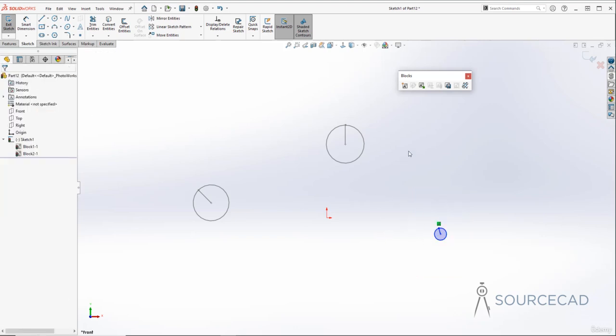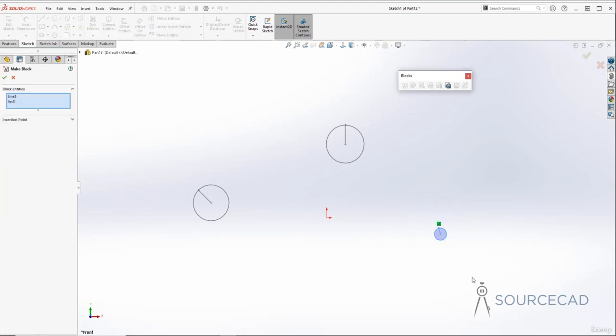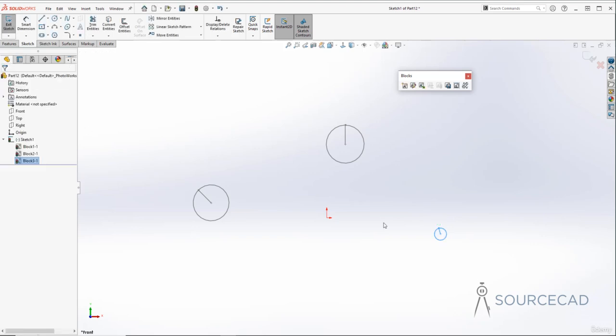So we have got three of these blocks. Okay, I missed this one, so I'll select it and I'll click OK, and there we are. We've got the three blocks added. So block 1, 2 and 3. Now using these three blocks we can create the mechanism. So for that, go to this option here on the blocks panel. We have the belt chain mechanism option.